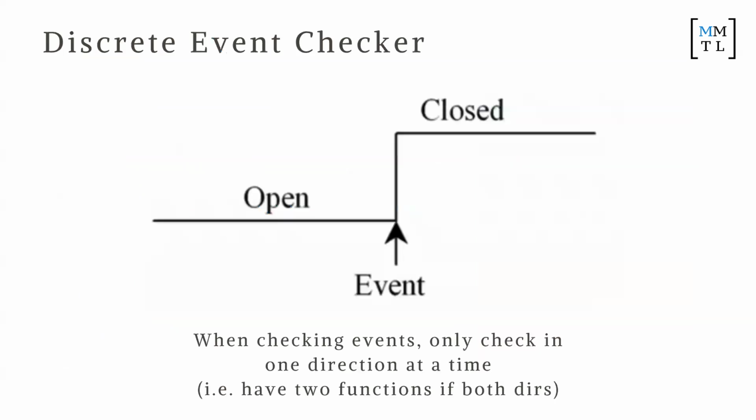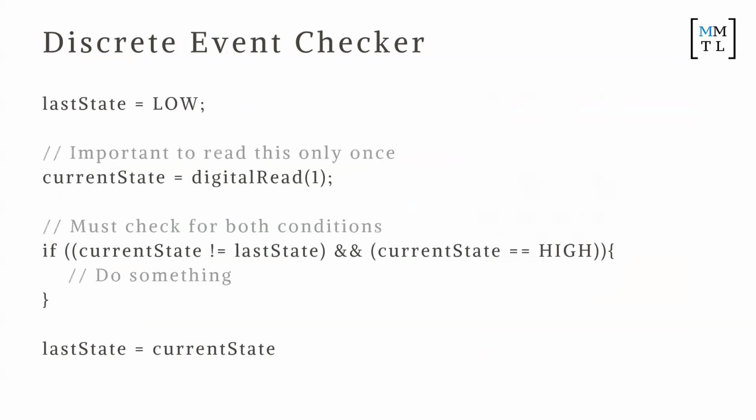We've talked about all sorts of common software patterns on Tuesday. One of the big ones that you might commonly see is when you're detecting a rising edge or a falling edge, which is what we did on Tuesday. It's really important to always have this code structure where you're checking if the state has changed and the state is what you expect it to be. Okay?